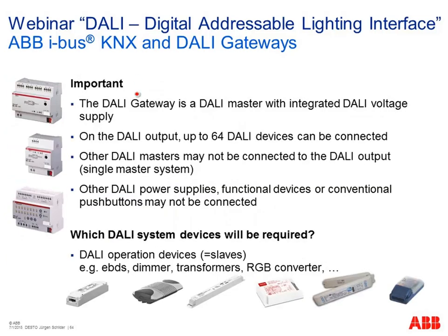But very important, when we use a DALI gateway, it's independent of the manufacturer. The DALI gateway is the master. And now with the existing DALI standard, it is only allowed to have one DALI master, which is the gateway. And then we can connect up to 64 DALI so-called operating devices, the slaves, the RGB driver, the universal, the DALI dim actuator, DALI switch actuator and so on. No DALI power supply, nothing, because the DALI gateway has the power supply built inside. So only so-called stupid slaves or operation elements can be connected at the moment to our DALI gateways.